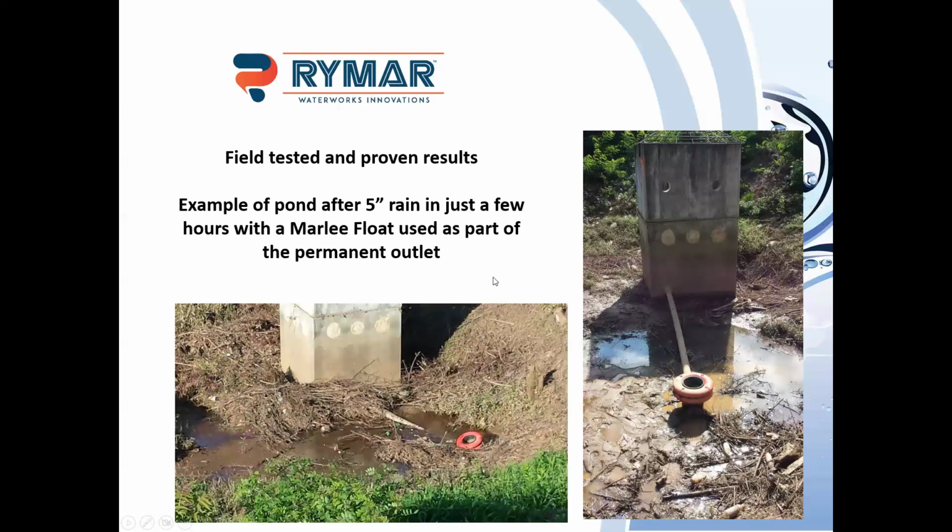About a year later, the owner is now maintaining this pond, and they had cut it and got a huge thunderstorm that washed all the cuttings down to the bottom of the riser. But you see the skimmers here. So you can imagine if all that debris was in this basin and had a 2-inch orifice just unprotected here, or even had some minimal protection, good chance it would clog up, and it would be very hard, if not dangerous, to clean out. With a skimmer in place, you can't see the rope on it.